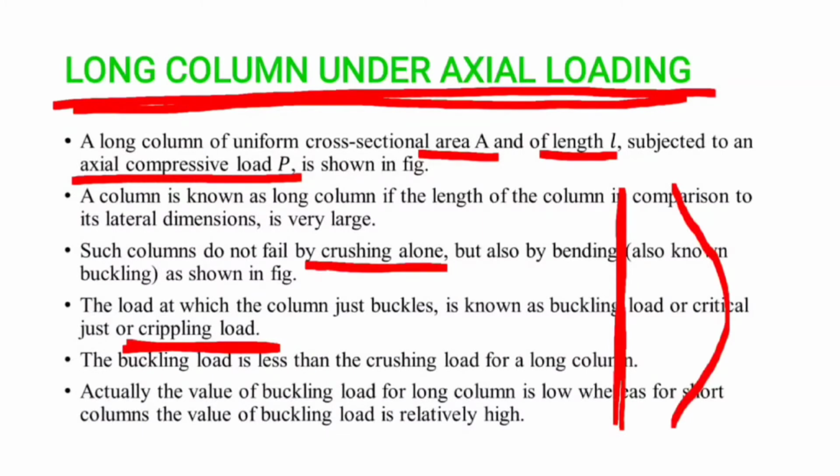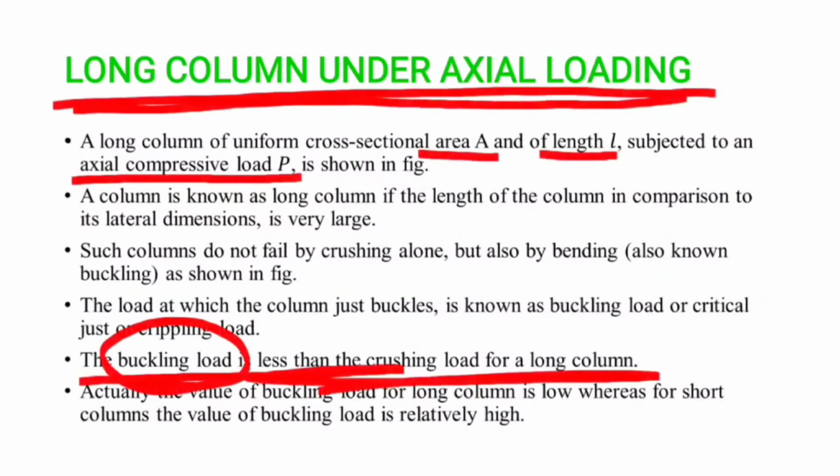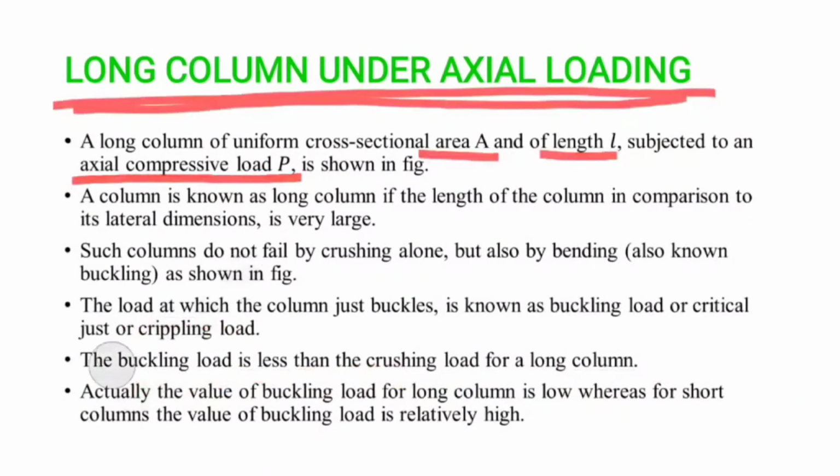The buckling load is less than the crushing load for long columns. Please remember this point. Buckling load is less than the crushing load for long columns. Actually, the value of buckling load for long columns is low, whereas for short columns the value of buckling load is relatively high.